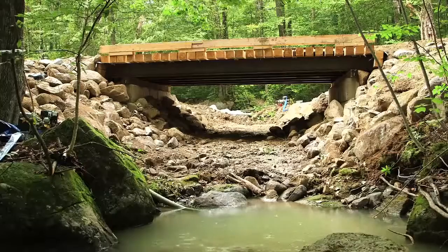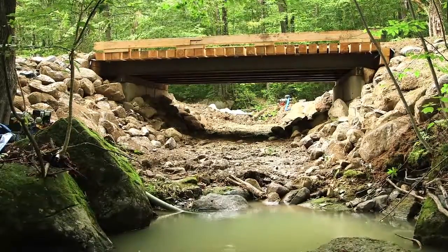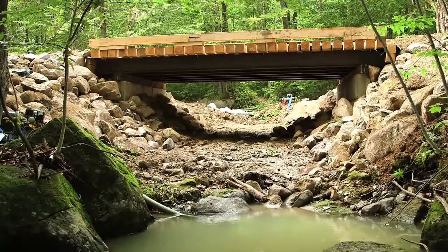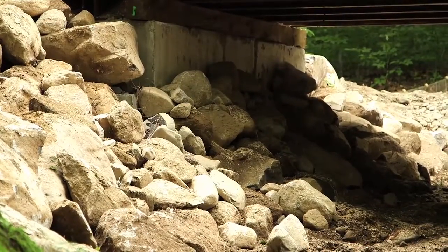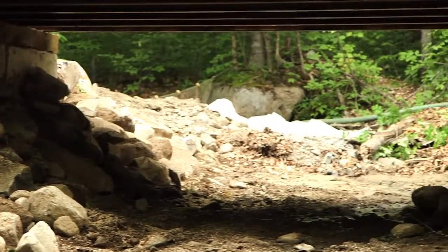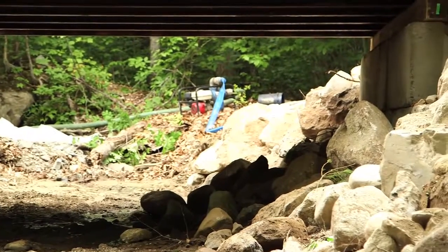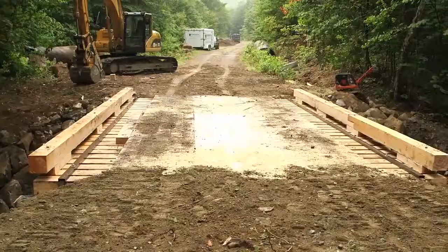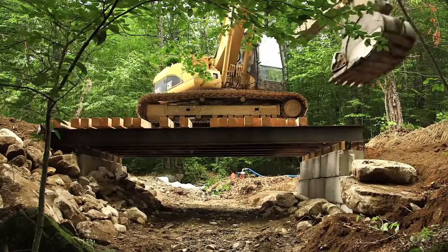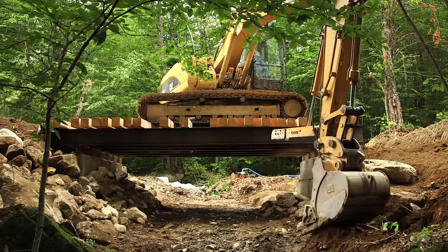A concrete block abutment timber deck bridge is typically used for smaller stream crossings on private land roads or other roads that have a lower traffic volume. Abutment heights are limited to 6 feet for the concrete blocks. Span width openings are typically 20 feet or less. However, up to 40-foot spans are possible using steel girders. These bridges are usually for one lane of traffic. They can be designed for a wide variety of loading requirements depending on the anticipated traffic over the bridge.